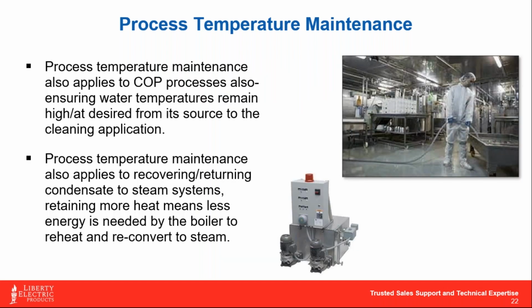All right. So when we talk a little bit more about some of these process temperature maintenance applications, sometimes not always about just sending a food product through a pipe, be it liquefied chocolate, syrups, who knows, chemicals. This also applies to things like your COP or CIP cleaning processes, where you've got to have high temp water to wash down kettles, things like that. And hey, it's got to be 140 degrees or it's got to be 120 degrees.